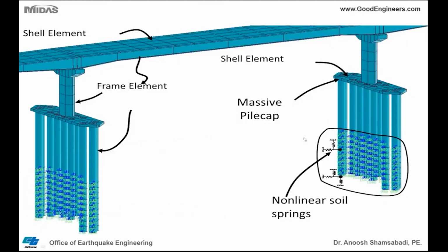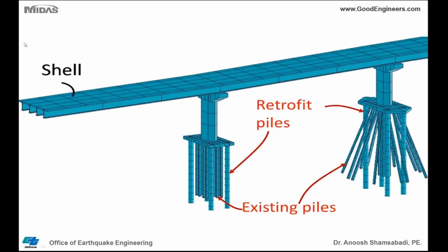Again, nonlinear springs, closer shot of the piles. These are nonlinear springs attached in Midas. One thing about the new version of the Midas, I don't know for those of you who are using Midas if you have the latest version or not, but you can basically develop your nonlinear springs outside Midas and copy-paste them in Midas. It has a new option now that you can develop your nonlinear springs, tension and compression, and easily copy-paste them in Midas and then attach at every node. You can attach those springs very easily. Again, closer shot of existing pile versus a retrofit piles here.